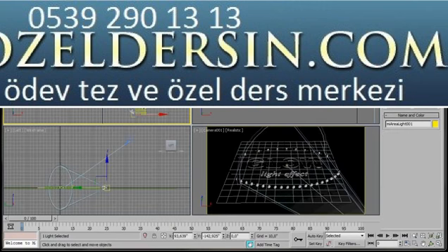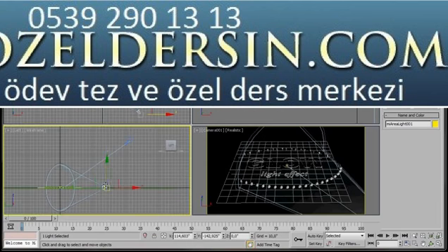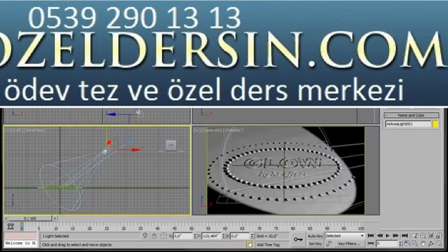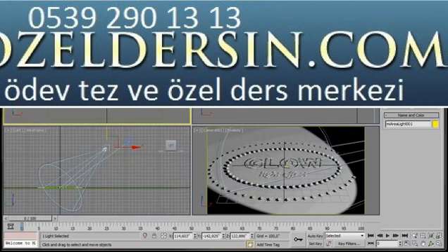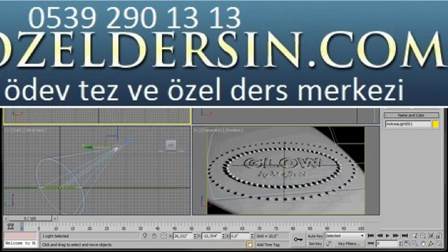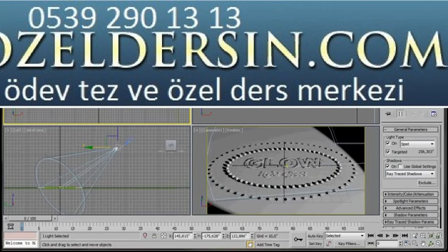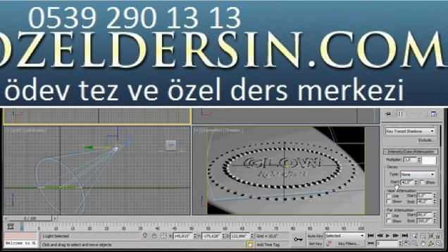I'm going to position it something like a 35 or 45 degree angle from the camera. And we can drag up our light in the left viewport. Try to position it the same as you see in this video. Then we'll go over to the Modify panel. And we're going to make sure we've got shadows turned on. We have ray traced shadows. In intensity, the multiply set to 1.